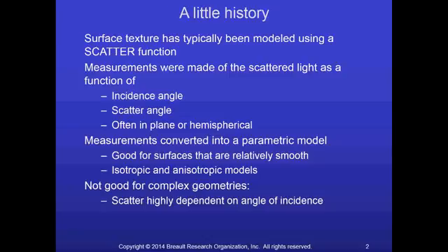And basically what's been done historically is a reference sample typically has been acquired in some fashion. So something that's been made to the manufacturing standard that will be applied in actual production. And that sample, that reference piece, is put inside some type of goniometer, and measurements are made. So light is sent incident on that sample, and then a detector captures the energy as a function of angle.